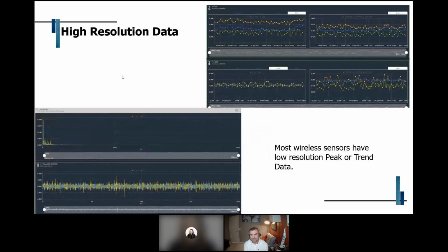You will want to be able to see your trend data. If you're not a vibration analyst, it's easy to understand that up is bad, flat is typically okay. It's also going to give you a multitude of information, from your peak vibration on all 3 axes. It also monitors temperature as well.